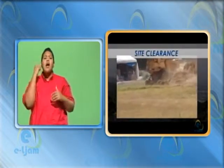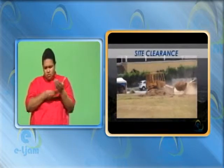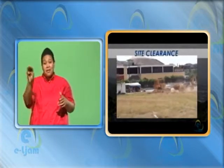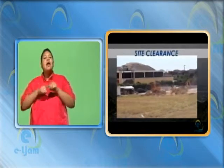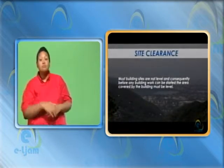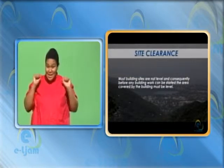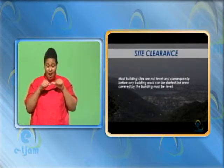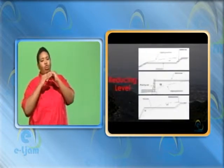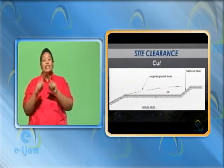The method chosen for carrying out the stripping of the site will be determined by overall economics. A 150 millimeter stripping depth is common, but depth varies depending on site. Most building sites are not level, and consequently, before any building work can be started, the area covered by the building must be level. This operation is called reducing level. One of three methods is usually chosen.